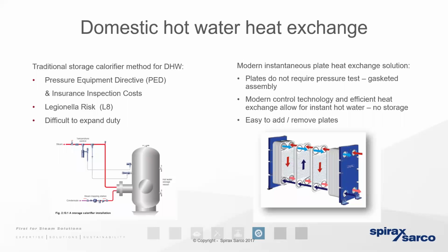But that volume of hot water that's held in storage can also bring a significant number of challenges that can quite often be overlooked. And that's because if we're holding hot water in storage under pressure, it's going to fall under the Pressure Equipment Directive. If we've got a volume of hot water under pressure at a high temperature, we've got the Legionella issue. And that's going to bring not only a certain amount of risk, but it also means that we're going to need periodic insurance inspections and maintenance concerns that are all going to come with some cost and a little bit of downtime whilst that maintenance and those inspections are taking place.